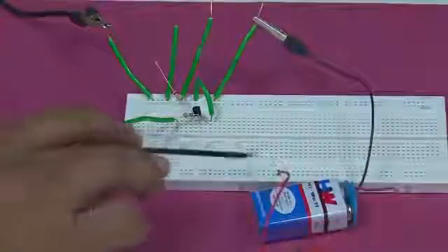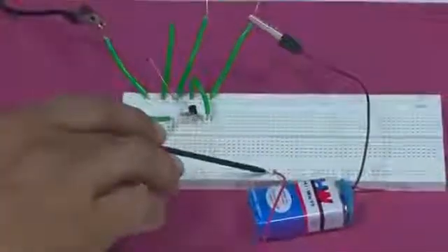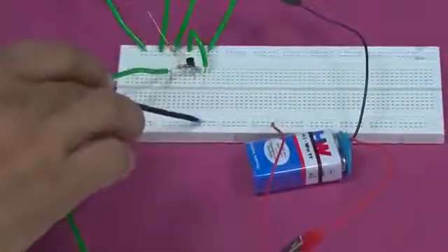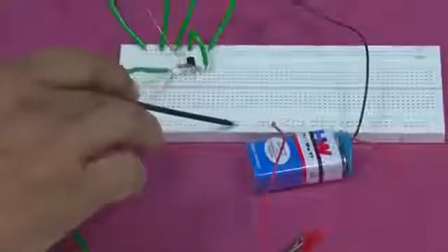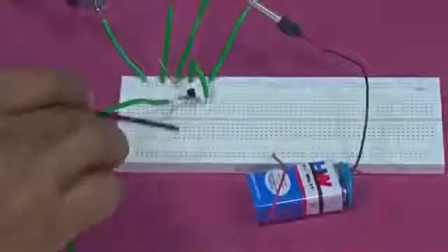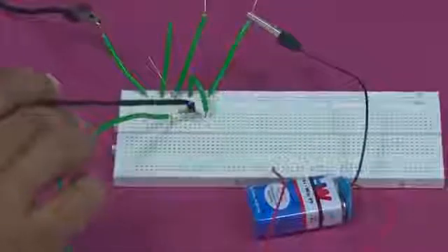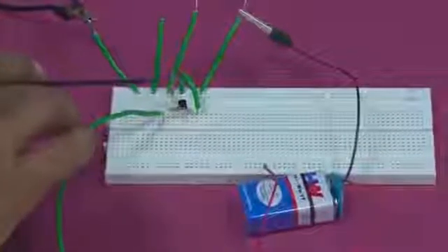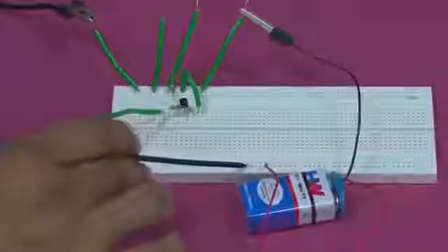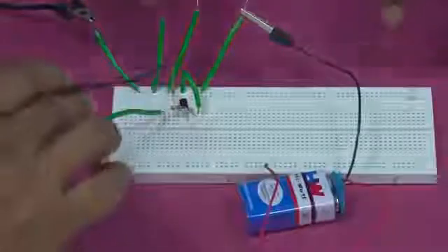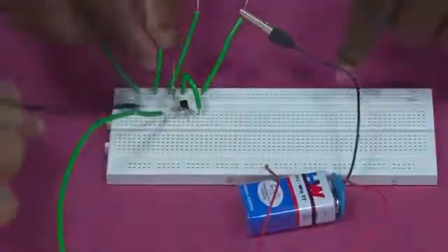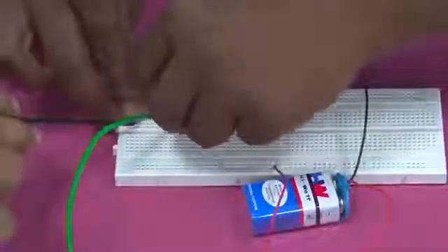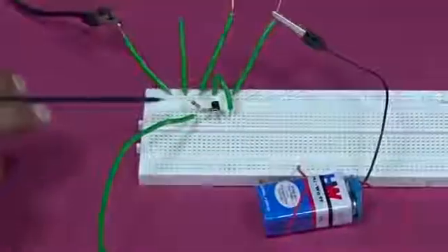Good. So, this is our 9 volt line. This whole line here becomes 9 volt. All these holes are at 9 volts. Fine. So, the collector has to be connected to the resistance that you have added, and the other part of the resistance should get connected to this line somewhere. You can join it anywhere you like, you can join it here. And then from here,